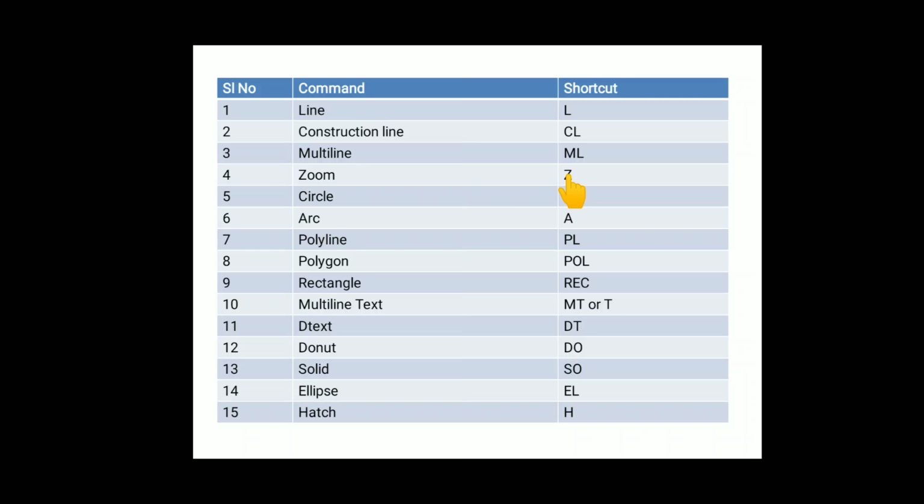This will help you when you do the drafting for various elements, like you are putting electrical detailing, plumbing detailing, as well as a structural drawing along with the architectural plan. So in such a confusion, you can use the layers so that your drawing will be easier.